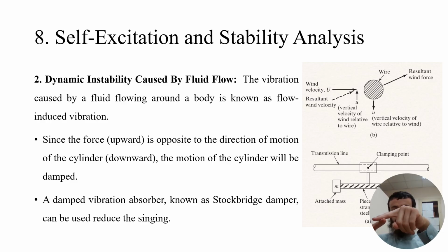When the air comes like this, it creates a vortex at this side. This vortex causes noise that we can hear during a very fast wind, and it also causes vibration of the cable. Over time, it could lead to the failure of the cable.